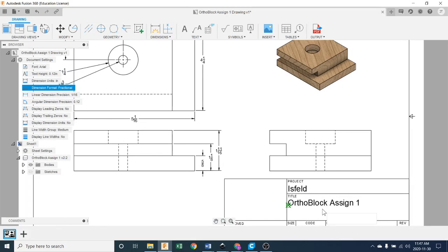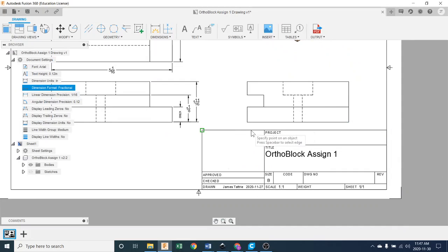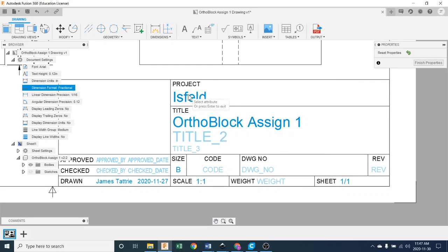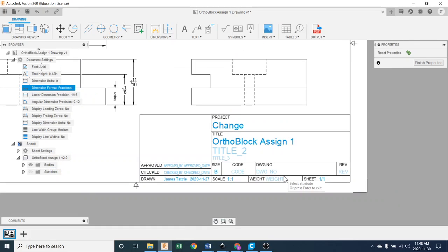And by the way, I didn't mention in the previous videos, but our title block down here fills in automatically based on the folder that I have my projects in and the file name I've given it. You can edit that if you want by double clicking on it, and you can get into your title block like I just did, and then double click on that, and you can change this if you want and hit enter, and it will be kept. It just automatically puts some things in for you, like your name based on your account with AutoCAD, and the date and the scale 1:1. So all this stuff has been added for you, but you can edit it if you want.